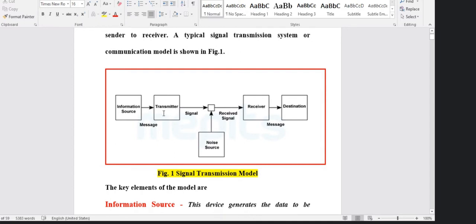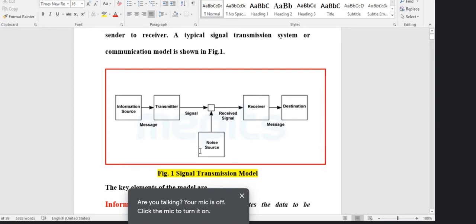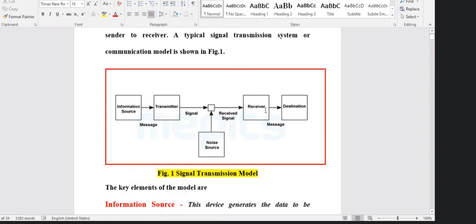After modulating the signal, if we modulate the information signal with a high frequency carrier signal, and for each separate voice signal we choose carrier signals having different frequencies, we can shift the frequency spectrum of the signals in such a way that the different signals will occupy different frequency bands. Then, when the different signals occupy different frequency bands, at the receiver it is not difficult for us to identify each signal from the other.